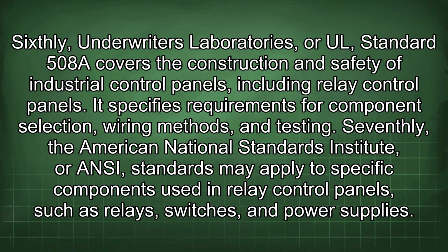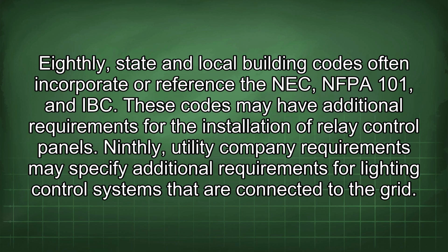It specifies requirements for component selection, wiring methods, and testing. Seventhly, the American National Standards Institute, or ANSI, standards may apply to specific components used in relay control panels, such as relays, switches, and power supplies. Eighthly, state and local building codes often incorporate or reference the NEC, NFPA 101, and IBC. These codes may have additional requirements for the installation of relay control panels.